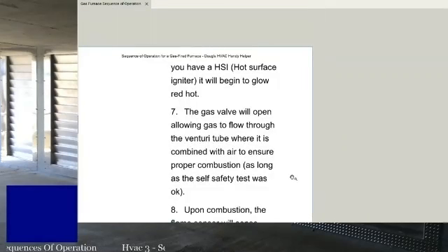As soon as the main burners ignite, there's usually a 2 or 3 second trial to make sure that the flame sensor senses flame. If the flame sensor senses flame, everything's good. So typically your problems can be a fan switch stuck closed, or a pressure switch for the induced draft motor stuck closed. If that's not stuck closed and the blower doesn't come on, nothing will happen.